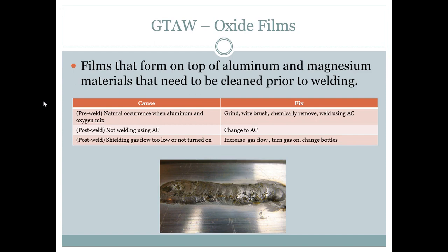Not enough shielding gas or too much shielding gas can lead to either contamination from the atmospheric air or turbulence in your weld, which is not helping clean it out, because you know, right, that the gas does some part in cleaning out your weld. All things to pay attention to.